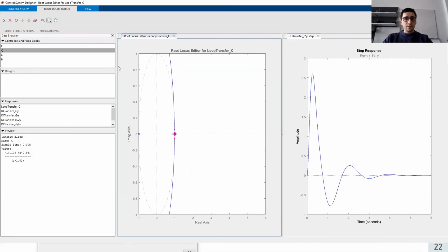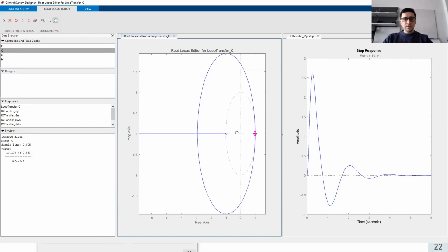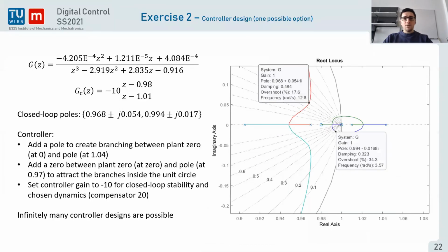If I unzoom, there's still one last one, but there's some branching, so it's quite difficult to see. But the poles on the left-hand side are just going like this, and they are mapped back here. Okay, so there is no pole here, no problem, no pole for this controller gain. And if I go on Matlab, this is why on the PowerPoint you end up with a controller like this one, where you have 1 zero and 1 pole, so it's something we can realize.